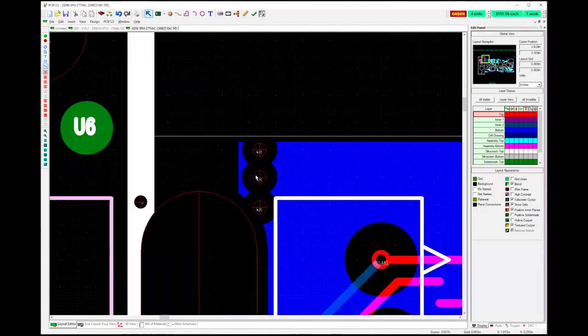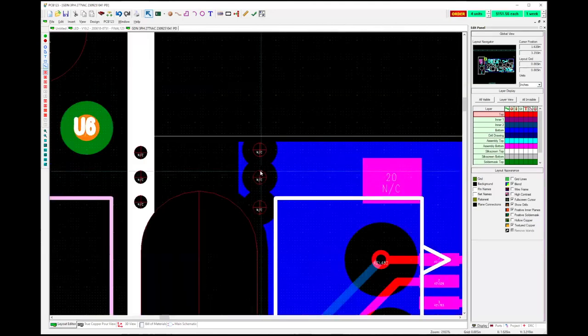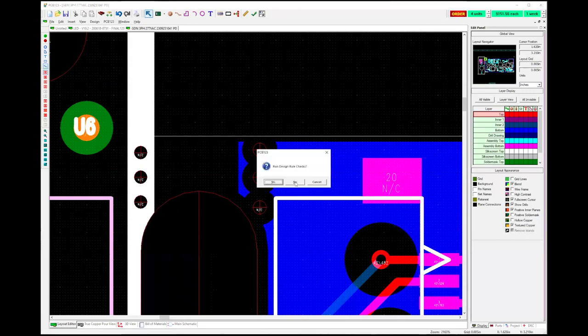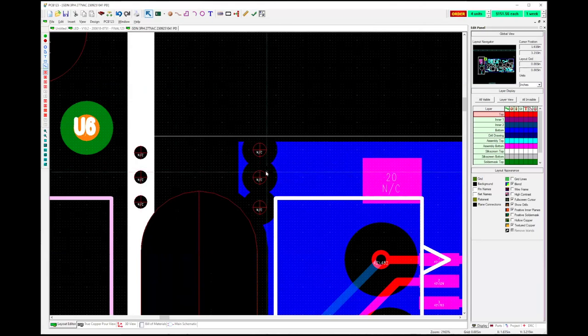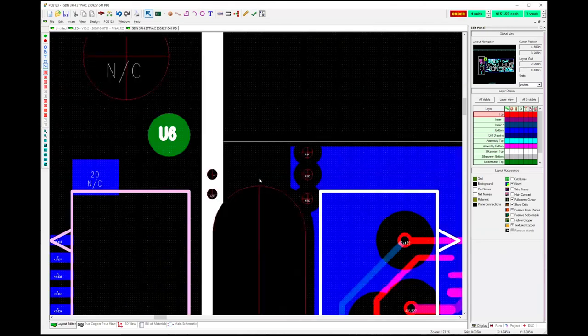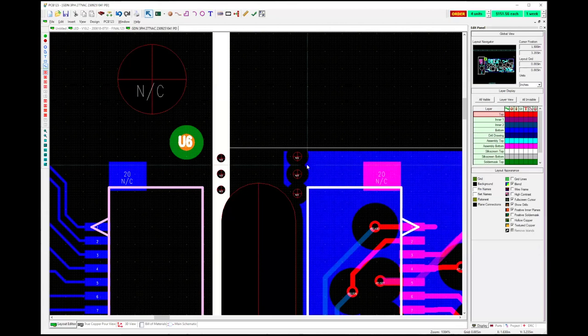they can be manufactured. If they're too close together, they'll just delete the drills because they're too close together. They'll snap drill bits, and they won't do those holes. So I think the rule is 10 or 15 mils apart for any holes. If you make them that far apart, you'll be pretty safe.